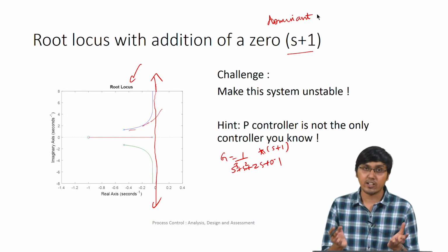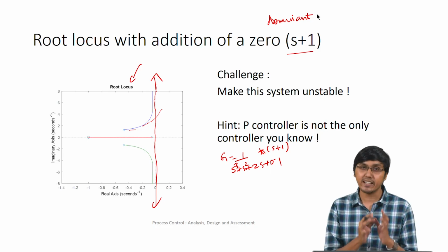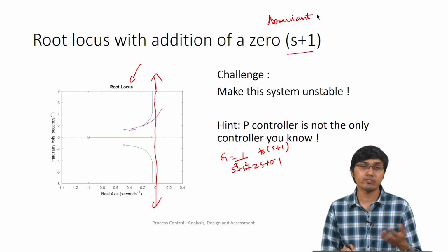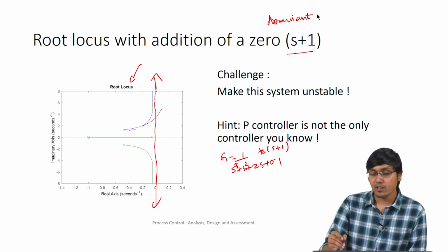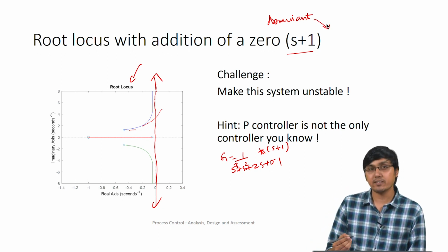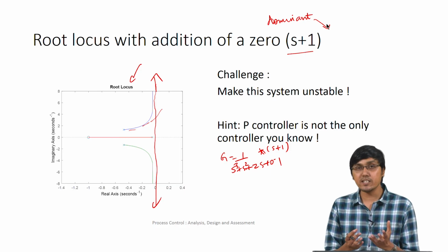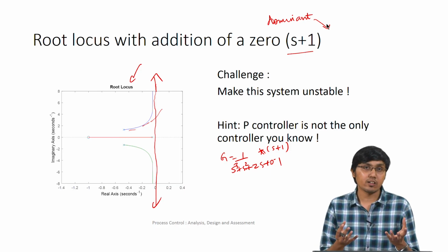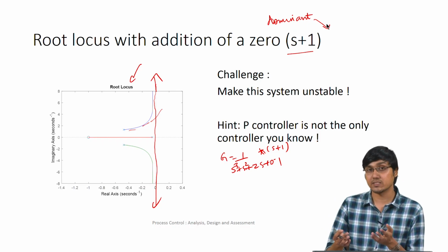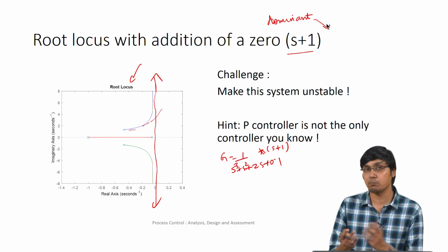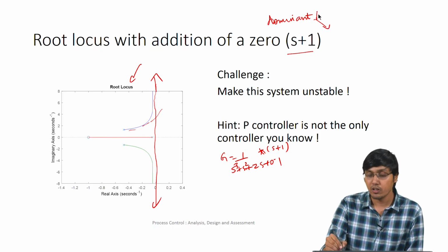We emphasize partial fractions to understand a lot of control concepts, because we can find out most of the concepts more easily when we imagine it that way. Basically, when we say dominant, which pole is going to have a bigger impact on the response of the system, that is what we call the dominant pole.